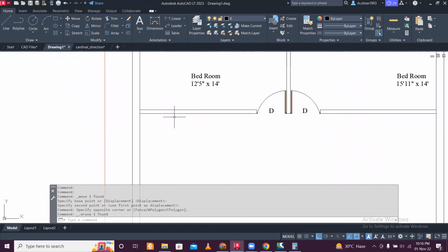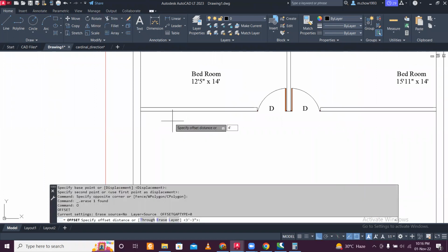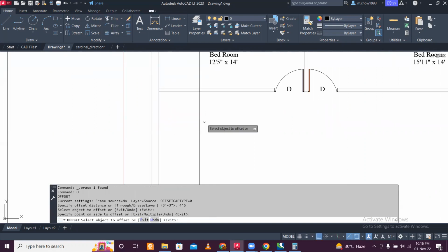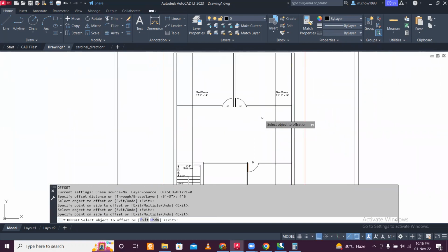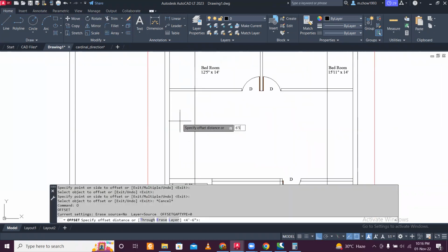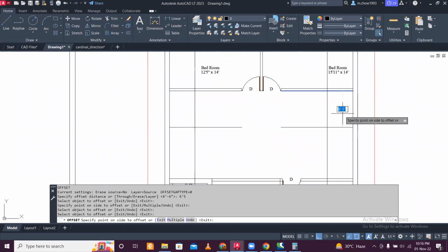Obviously, the bedrooms will need some attached toilets. So let's keep toilets here 4 feet. Can give toilets inside in these two sides, but in the space, so here we can give, right. The back side also we can give toilets, but inside since your space, so we are giving it 4 feet 6 inch and 4 feet 6 inch, right? And then let's take 6 feet 5 inch, right? 6 feet 5 inch from here, 6 feet 5 inch from here, and then the 5 inch walls.